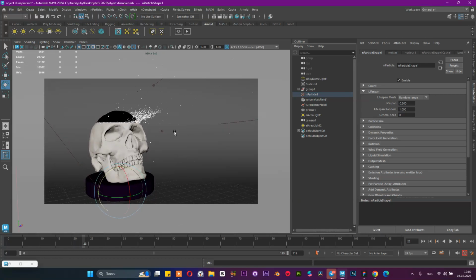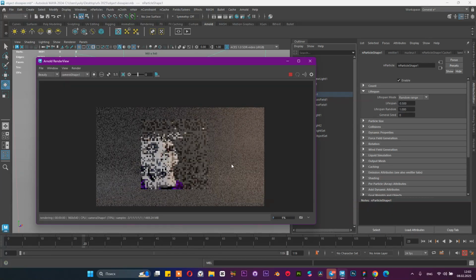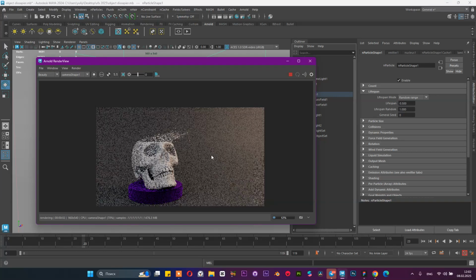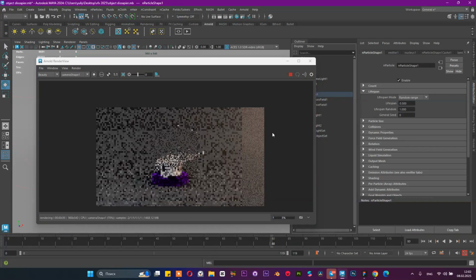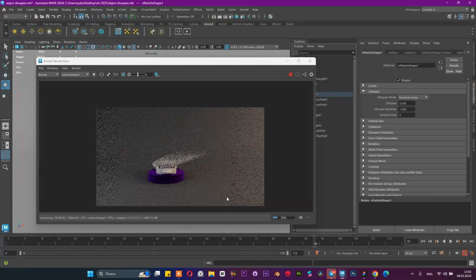The cache means you recorded your simulation to the memory, and Maya doesn't re-solve this particle simulation every time. It's really easy to use cache when you need to check your render through the timeline, and you can switch between frames and see the particles at this time. And this cache will help you when you render your simulation.